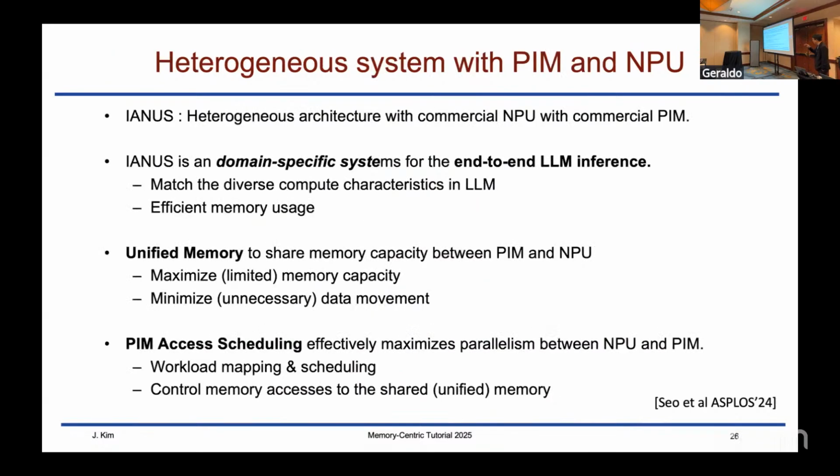But again, the key thing here is that it was a unified memory system such that you share the memory between the PIM and the NPU, and you avoided the unnecessary data movement. The other interesting aspect is everyone has heard of memory controllers and memory access scheduling. We had to come up with a new catchy name here, so we called it PIM access scheduling, because now the controller is not only responsible for the normal memory accesses to the shared memory unit, but it also has to schedule the PIM commands as well. So that's the new challenge that goes with this particular system.